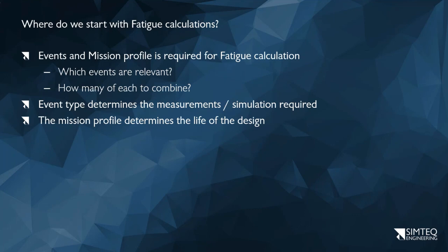And then the other event that's actually important and easily abused by mines is the startup and shutdown transient, where we typically operate it at a speed above the first natural frequency, actually probably above the sixth one. If you now start up and shut down, the speed of that imbalanced mass as it slows down will go through all of those modes, and the excitation then causes pretty significant stress at that point in time. Okay, so that's it.